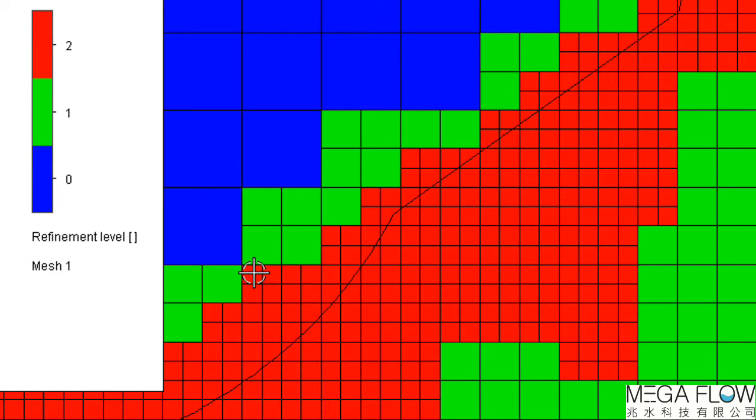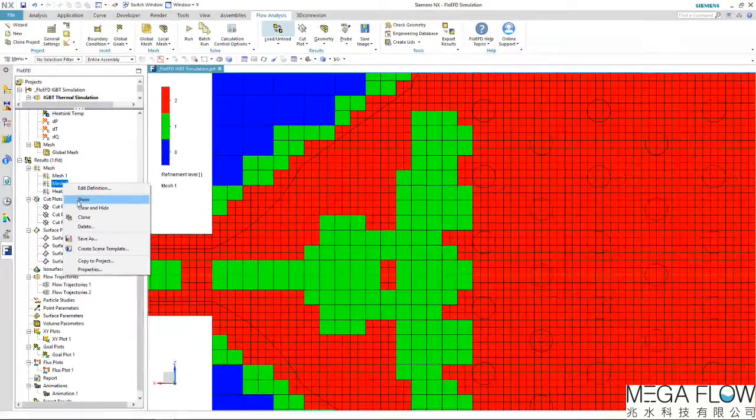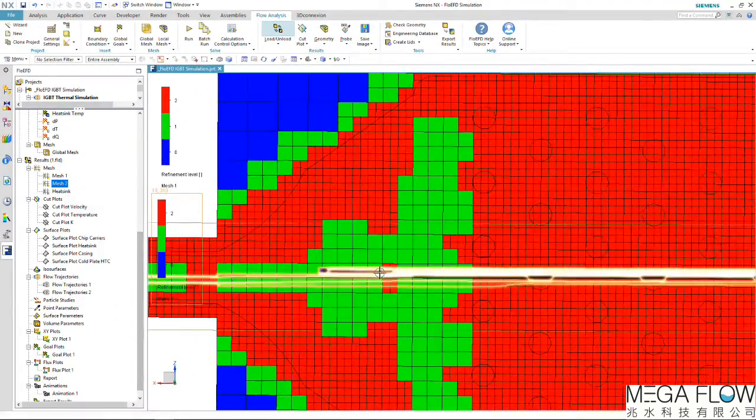This Octree method performs 2 important tasks. First, the aspect ratio of every cell is identical. The smallest cell has the same aspect ratio as the base mesh. The second is that the growth ratio is restricted to a single level to avoid very small cells transitioning into large cells. These are both important for solver robustness and convergence behavior.